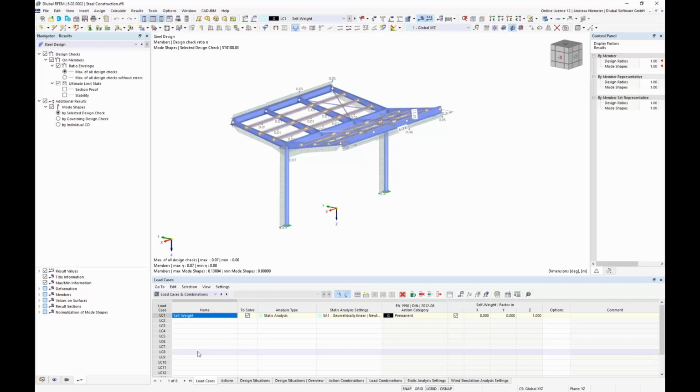And we can fill it now with maybe wind load cases. So if you generally have to design the structure, you create wind load cases based on a standard. For this type of model, we know our standard offers us load schemes for canopy roofs that you can apply. This is maybe quite exhausting because you have to calculate resulting forces for every wing and set it up. And today I want to show you how you can solve this with a CFD-based analysis.